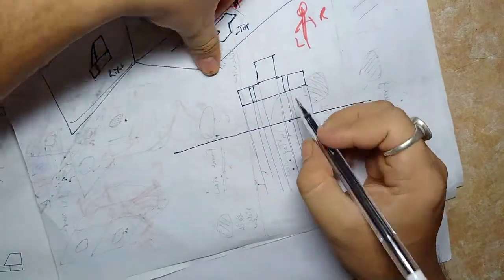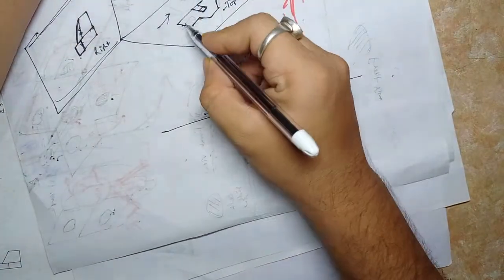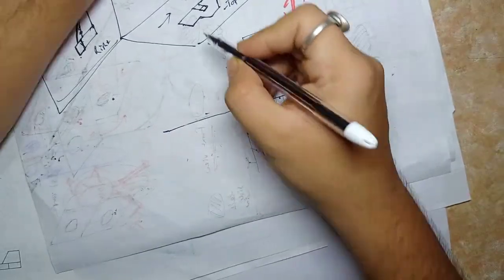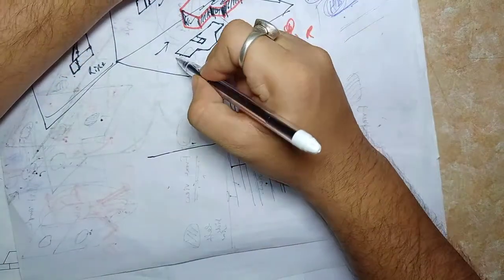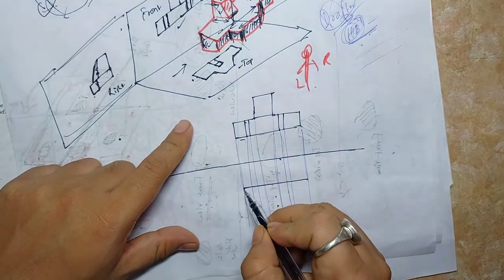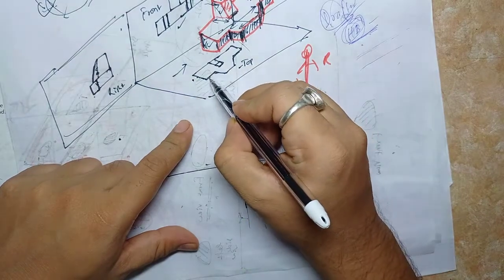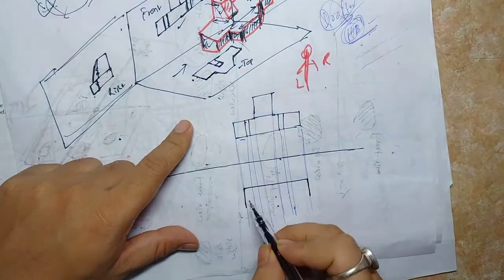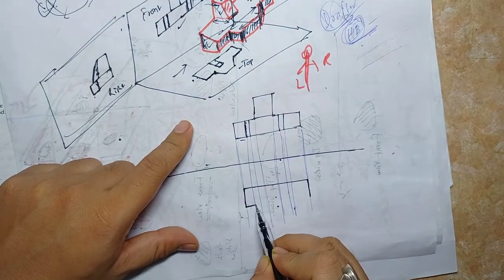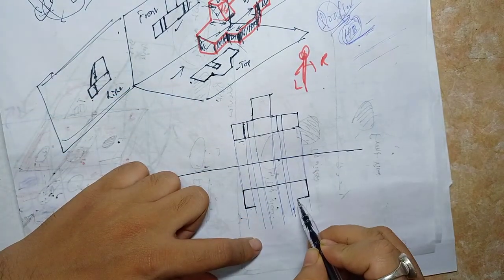Now how to obtain it? Since you already know your top view will look like this, that will help you. Now you draw the line here, because that will be exactly equal to this edge. Right, fine. And then you know this dimension here, so you draw that dimension here, equal to that one, and a similar one on this side. Now you know the dimension of this line. That line is this edge, so you draw up to that, because you already have the projection for that line. You don't have to measure it. For here also you'll draw it up to this.